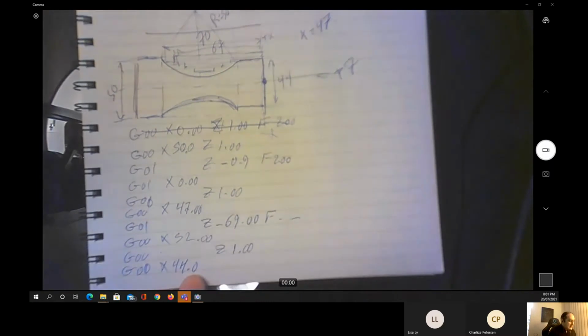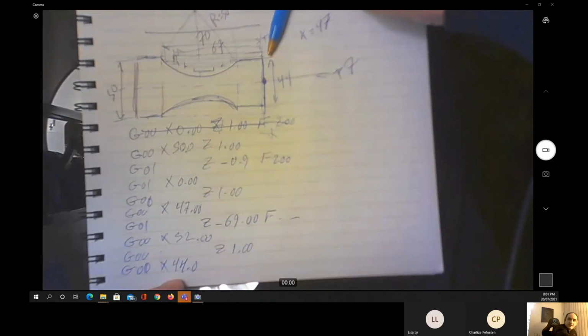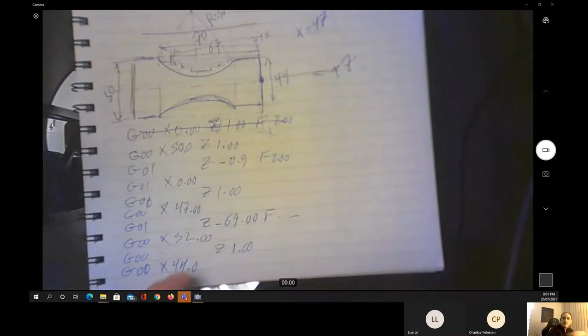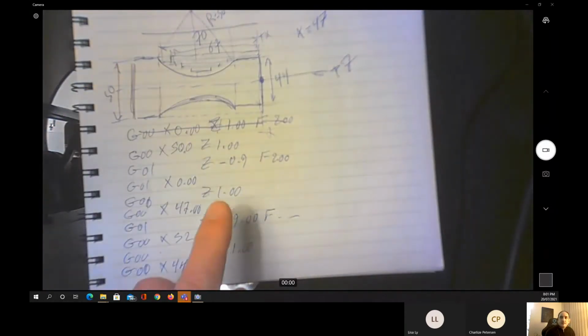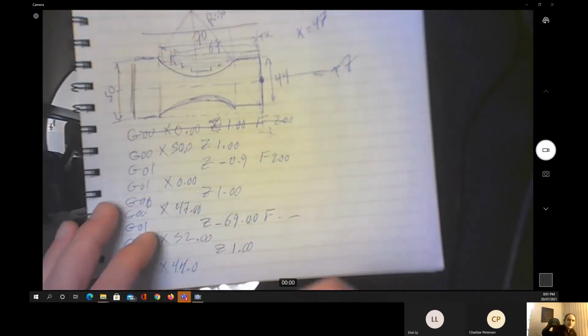Okay, now what happened is that my cutting tool is in this position, and I'm going to send it, sorry, in that position, a little bit higher, and it's going to go all the way to here to make the new cut where the diameter is going to be reduced from 47 to 44. So I move 3 millimeters in the way.